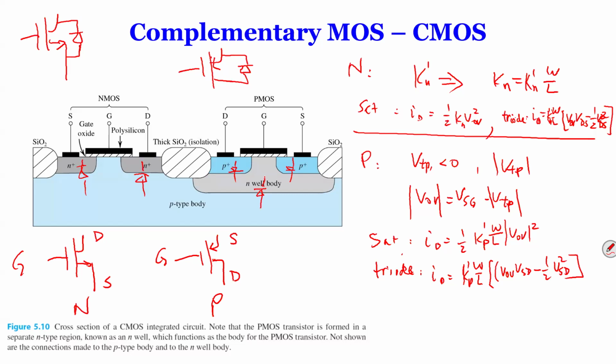So you have a lot of diodes. Some of them call these body diodes. So we have to be careful with the body diodes because they actually can flow current in one direction, even when the MOSFET is off. So if we sometimes use this as a switch, we have to use two of them back to back.